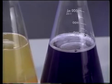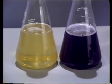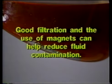To reduce this problem, most systems using fire-resistant fluids have large reservoirs to allow plenty of time for air to escape from the fluid. Synthetic fluids and water-based fluids also tend to trap and hold dirt longer than petroleum fluids. Good filtration and the use of magnets can help reduce fluid contamination.